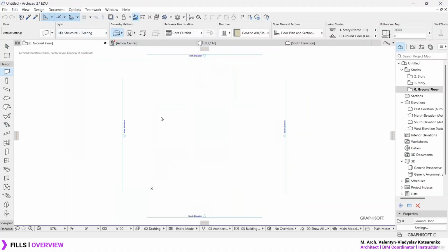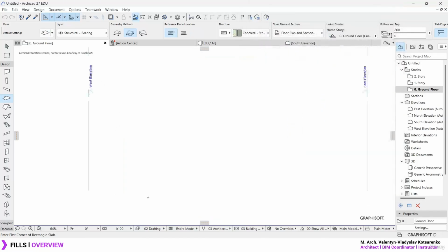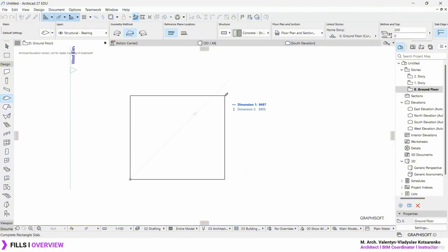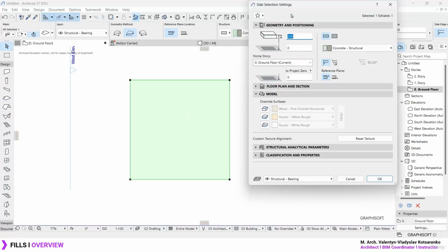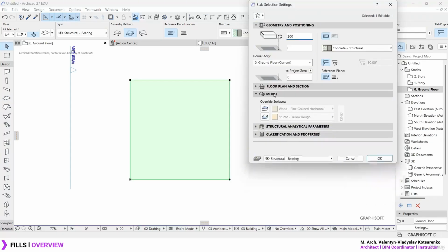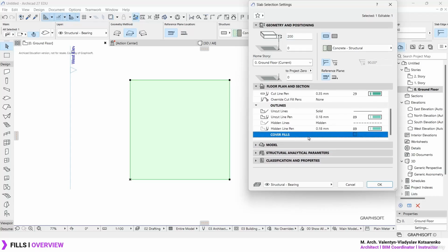How about we, for demonstration purposes, just create a basic type of slab, and let's make it 200 in width. Let's create a basic slab which is 10 meters by 10 meters over here. And if you remember, something we already covered in Basic BIM Framework with ArchiCAD, the first course, or the second one, you could apply completely custom cover fills to your slabs.